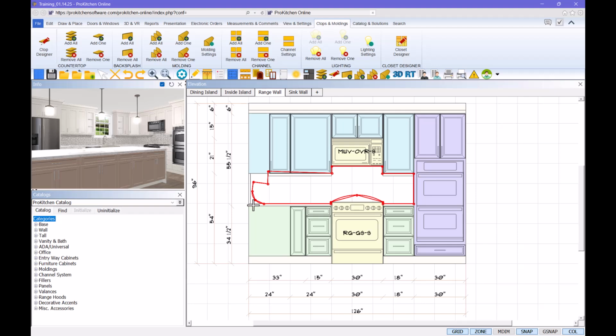Back in the additional right-click toolbox on a point, we will find Bevel. Again, once selected, you may only make this edit towards the interior of the item. This time, an angled line will appear that will essentially cut the corner off and provide a smooth straight line in its place. Once the beveled edge is in the desired location, left-click to secure. There will then be an additional 2 points and a single line which you may select and continue creating edits.